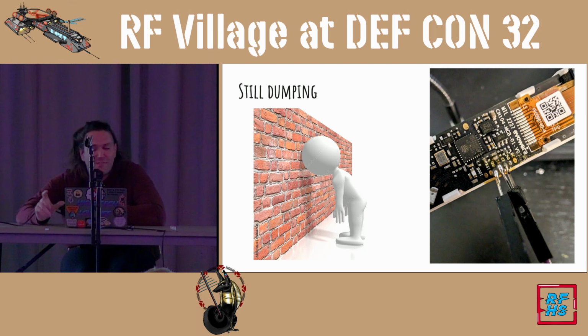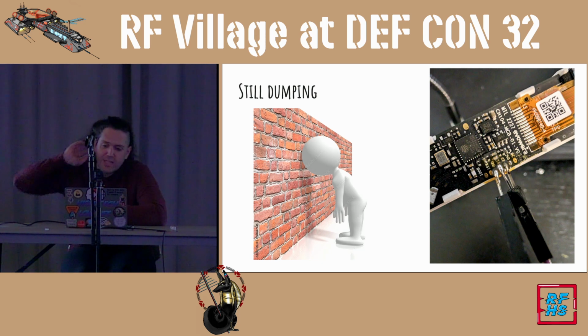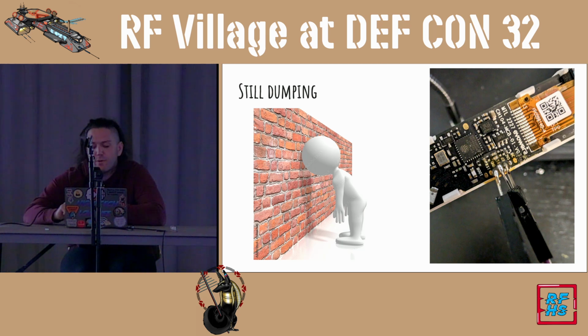So I don't have any of those fancy PCB probe-out things, and so when it comes to hooking up stuff to a circuit board, I'm usually just trying to solder stuff on there in the grossest way, because I'm not the world's best solderer. So essentially, solder up to TX, RX, ground. We don't need to supply 3.3 volts through this because we can plug it in through the USB-C adapter at the bottom of it, which is how the device is normally charged. And that's good enough to get it turned on and trying to start talking to it.